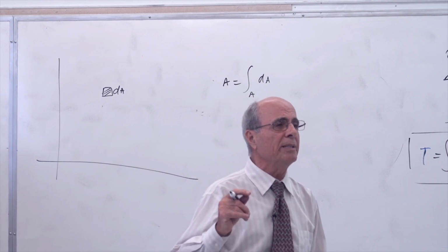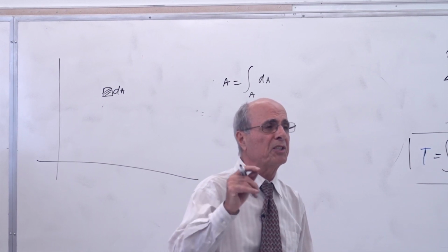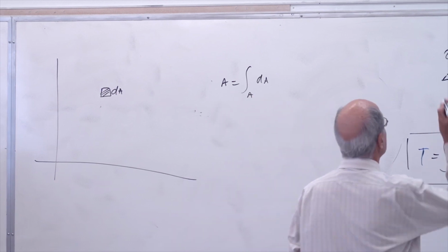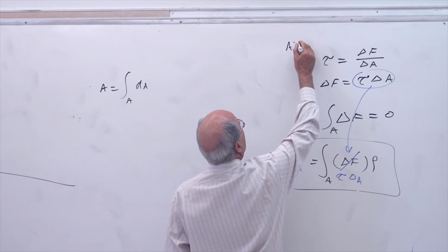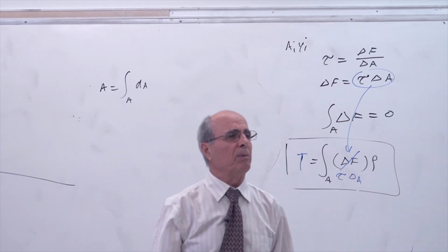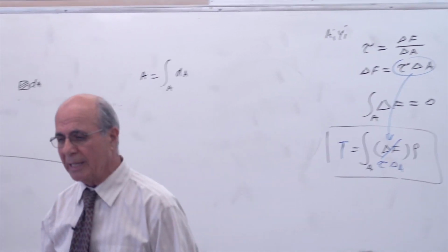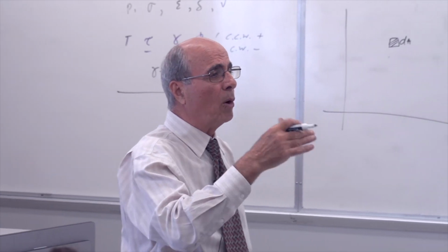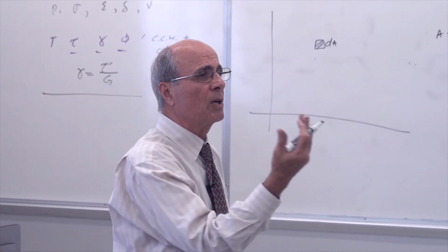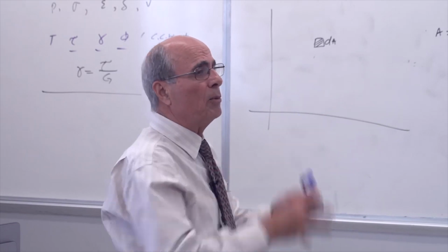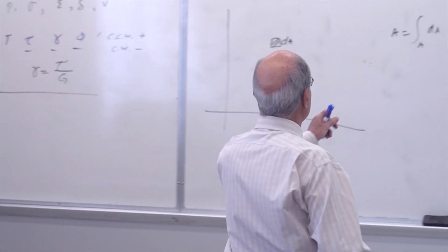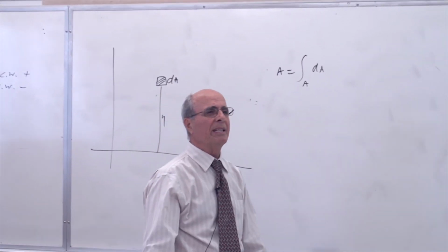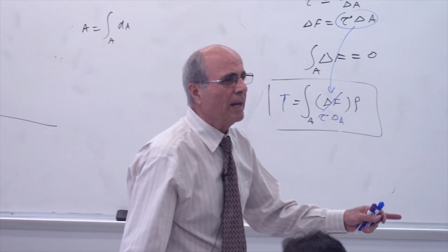You need to calculate the Q. Q was what? Was the first moment of that area with respect to x-axis, and anytime you write in your table A_i, y_i, that is the Q. Everybody understand that? I don't know whether you learned it that way or not, but the numerator of x bar and numerator of y bar are the moment of the area about the x-axis or about the y. You get the area multiplied by y, yes or no? Exactly what I'm going to do. This is the area multiplied by y, yes or no? That is the Q about the x-axis.